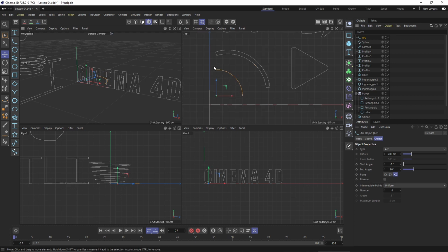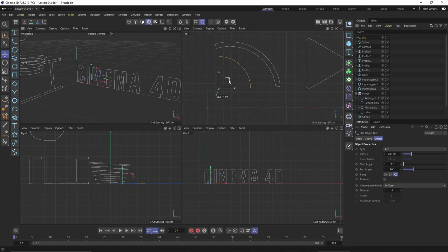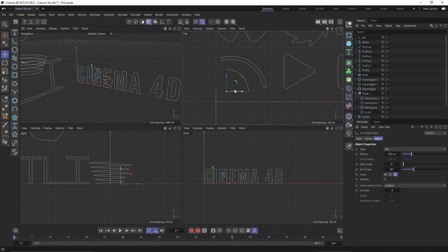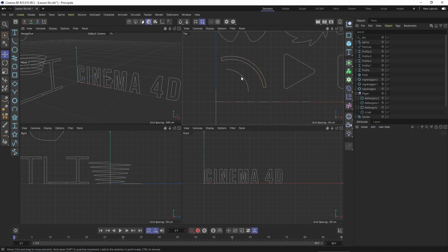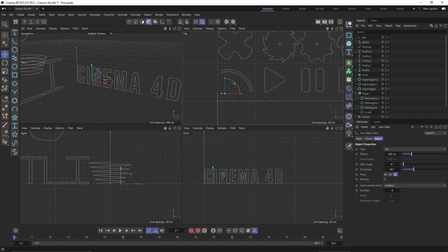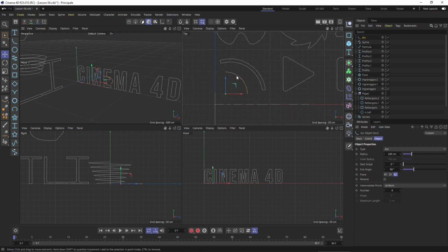Now this is an open curve or an open 2D shape. It's not closed. So what's the difference between this one and this one? Well, if you think about 3D modeling, when you extrude this, you're going to create a surface. Instead, if you're extruding this, you will be able to create surfaces, but also a solid. So when you create shapes, probably it's always better to close them if you need to create 3D models from them, 3D objects. Otherwise, you can keep them open as you wish.